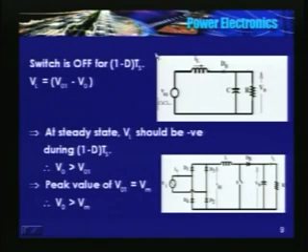So voltage across the inductor when the switch is opened is VO1 minus V naught. This should be negative. So therefore V naught should be higher than VO1. But then VO1 is a rectified sine wave. It varies from 0 to Vm. I told you that V naught is held constant.